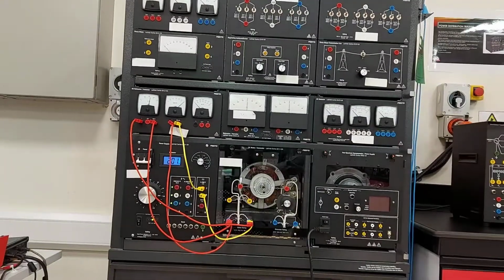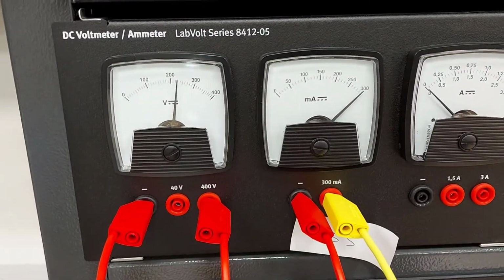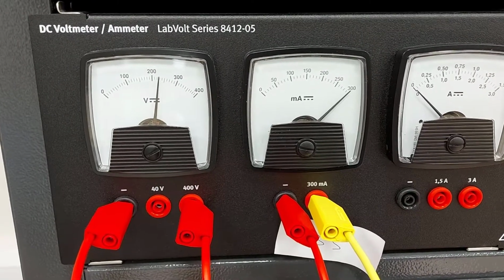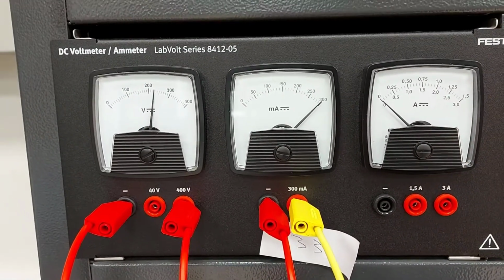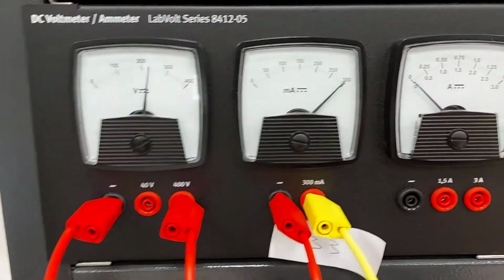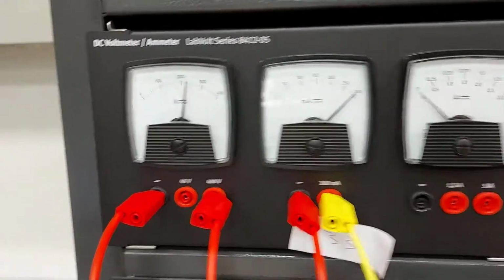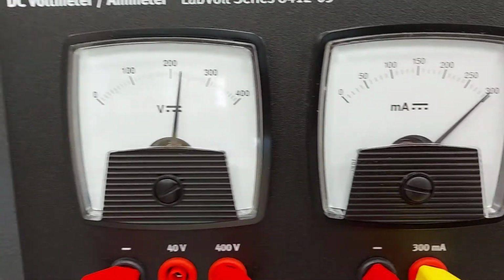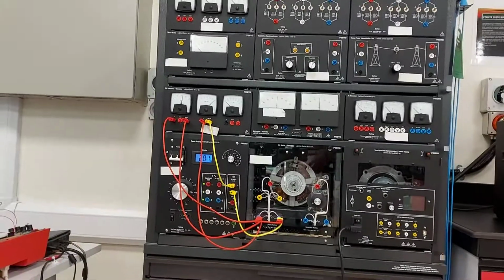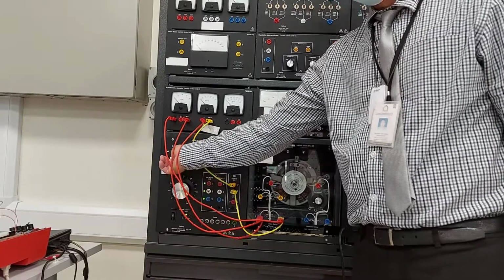Let us try to record. Please get your pen ready. That is the voltmeter on the left side and the ammeter on the right side. That is 0.3 ampere or 300 milliamps, and the voltage is about 230 or something. Just read it. Now return the voltage to 0 and turn off the power supply.